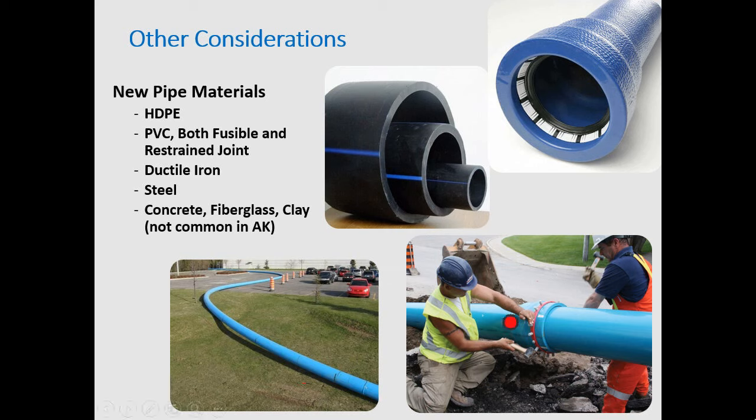They hammer those plugs in, and it's a bell and spigot, so your pit and your access pit can be minimized with that. They're using ductile iron in places. I was in Europe last summer and had a picture. This isn't my picture, but they were using this product on a pipe bursting job in Europe. Pretty cool. So they're using a restrained joint ductile iron and then dropping it in their 20 foot. So their pit only has to be 20 foot long, 25, to make sure they have room for the equipment. And then they're using steel.